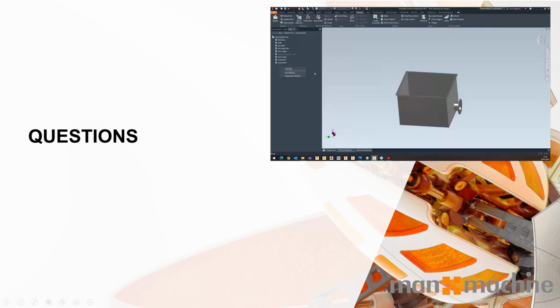The reason being is that the content center adds a lot of extra drag to the model. Not drag as such, but it adds a lot of unnecessary parameters. It makes it a little bit messier, and it also works slightly differently. It adds extra work planes. There's extra things from the content center. So I would generally remake them myself for iLogic purposes if they're going to go into an iLogic model.